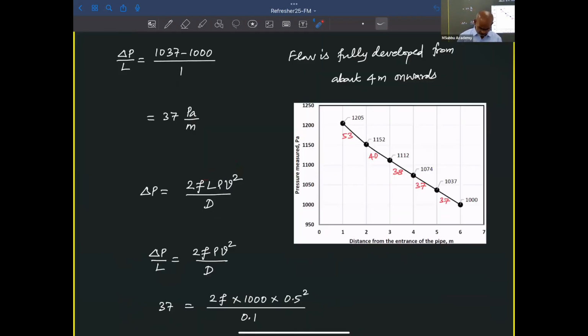Whereas in civil and mechanical books, you will have the relation with what is called FD, the Blasius or Darcy friction factor, which is actually 4 times this value. Because of that, instead of 2 here, we will have 2 in the denominator. In those books, we won't have 2 here. Instead, 2 will be in the denominator, and F refers to the Darcy friction factor.